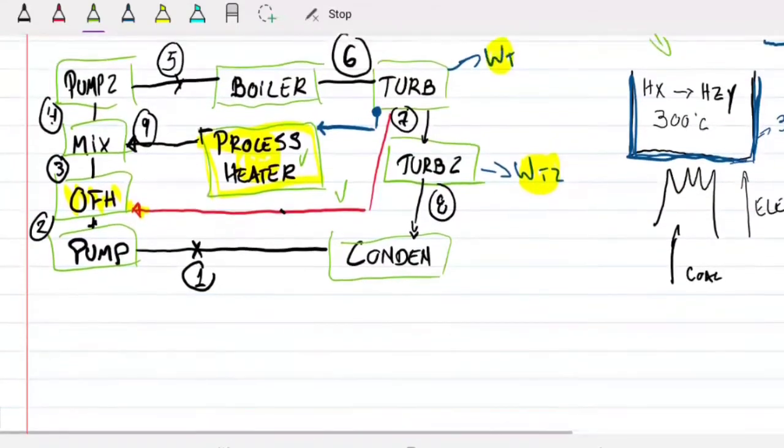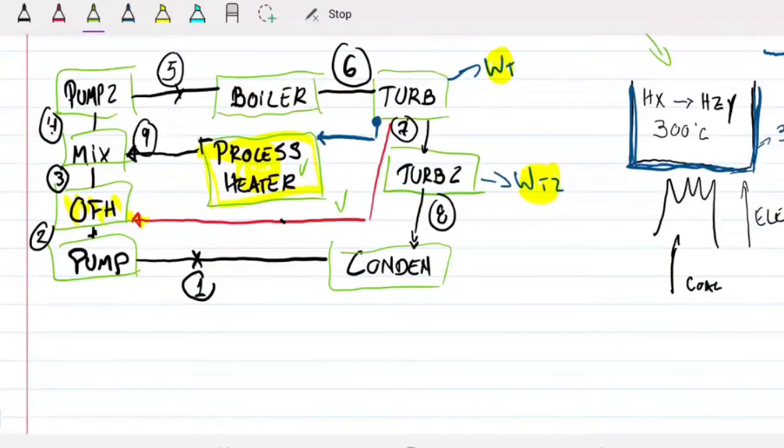Okay, so I'll draw the TS diagram for us now. And I know it looks messy, but it's not. The TS diagram is not as bad as this. Okay. The other thing that we know before I go to the TS diagram, is y, and I'm going to read off the problem statement here. 35% of steam is extracted from the turbine, and the remainder expands to 10 kilopascals.